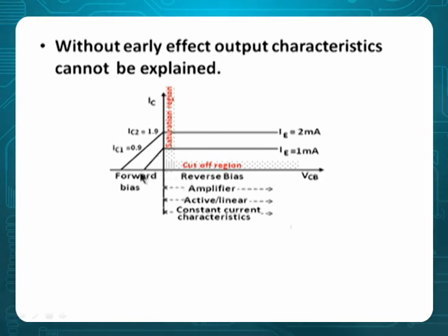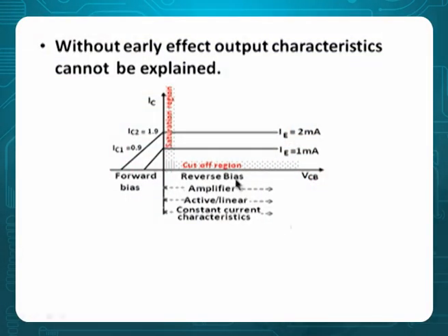Now, this is forward bias because we are giving negative voltage. Negative voltage given to N is forward. And from here it is reverse bias. Therefore, this can be the saturation region and this is the active region. Below, down the current, that is called cutoff. This is not cutoff. This dotted line below 0 current is cutoff. And this is saturation, and the remaining portion is the active region.